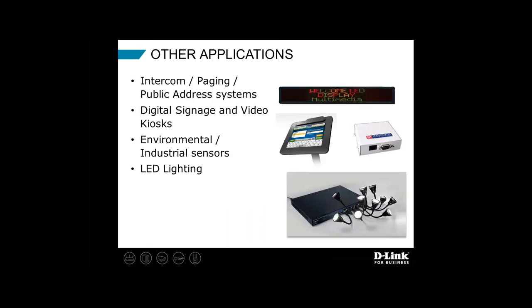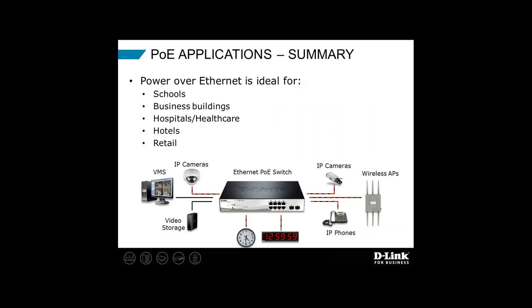A lot of other applications for PoE that we don't have time for. There's intercom and paging and public address systems. Certainly digital signage as we go from the AT to the new BT spec. There'll be more applications for signage and video kiosks. There are a lot of environmental and industrial sensors that you can get today that are PoE powered. And then, as I mentioned earlier, LED lighting is a new application that's coming fast and furious, and I see good things happening there. So in summary here on this section, a lot you can do with PoE.